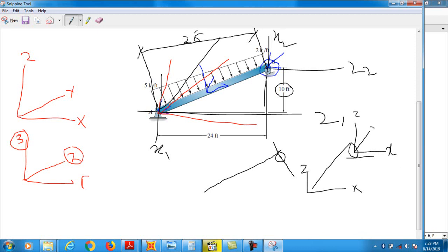This is its y-axis. We need to rotate these axes by an amount which brings these local axes perpendicular to this member. What I mean is that these local axes will become in this shape. x comes here, z comes here, and y comes here. Clear? So we need to rotate now these local axes of this joint.